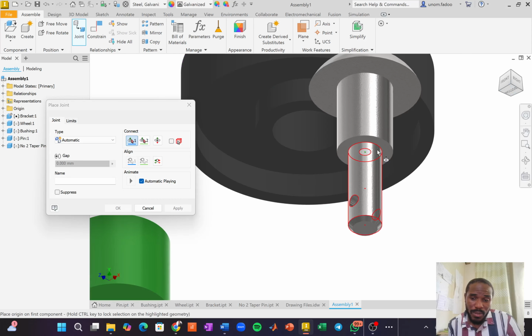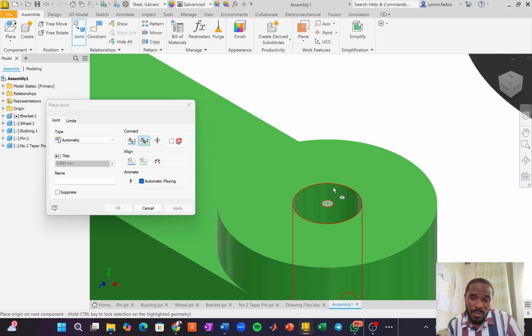I will select this. Now, once you hover over this, you see three different points where you can create a joint, right? If I press Control on my keyboard, then I can jump between those points. Otherwise, as you move, it might change and go somewhere else. But the joint I want to create is that top one, because this is the one flushing. I don't know where the midpoint really is, because this is not the same as that. So I want that point. Then I'm going to come this way and select also that top point. Okay, that's where I want it to be.